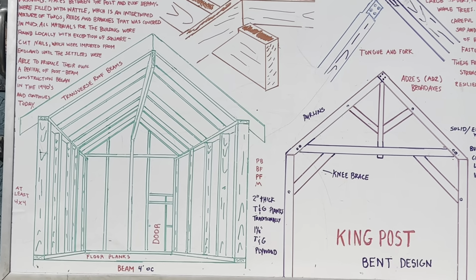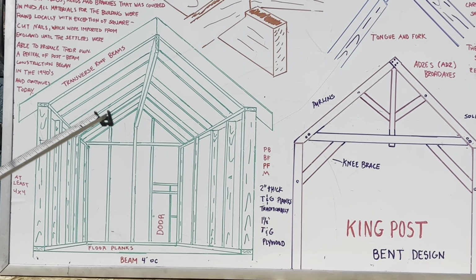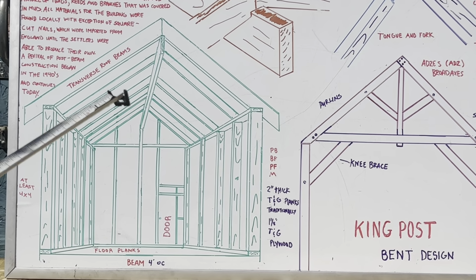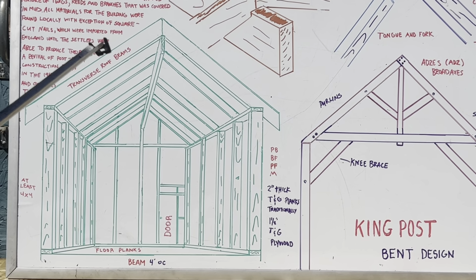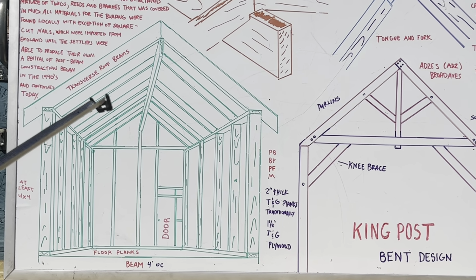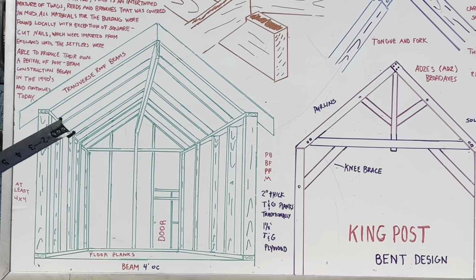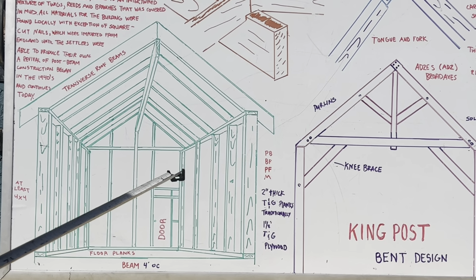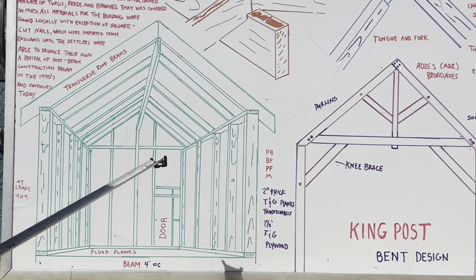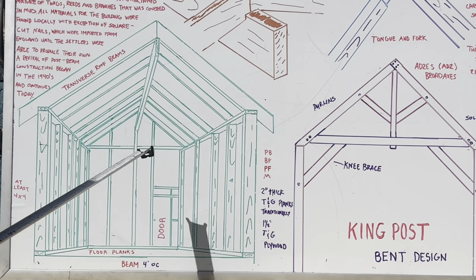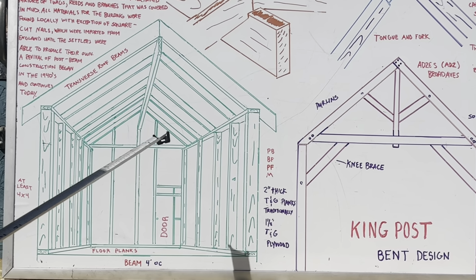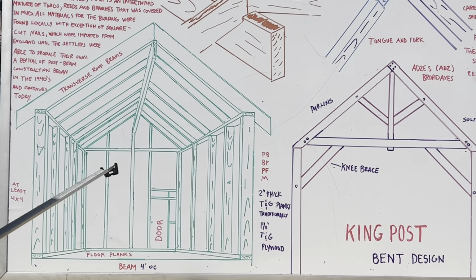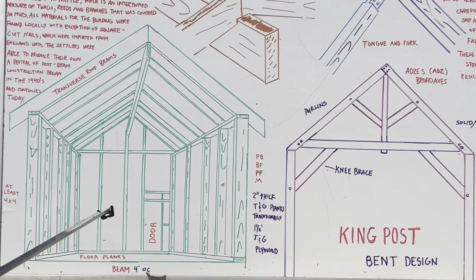Okay, now, there's basically three types of post and beam construction, okay? Now, post and beam, which this is an example of, was sometimes also called plank and beam, okay, because they used 2-inch thick, tongue and groove planks on the flooring.